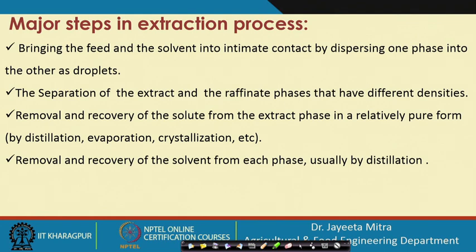Okay. So, the feed and the solvent you have to bring into intimate contact by dispersing one phase into the other as droplets. Then comes the separation of the extract and the raffinate phases, which have different density. This is applicable when we talk about liquid separation, because in leaching we mention the overflow and underflow. In case of liquid extraction, we name them extract and raffinate.